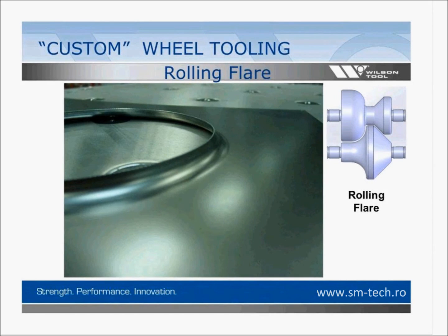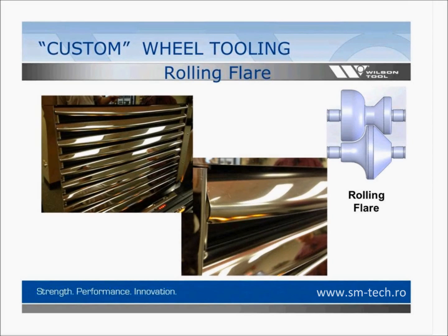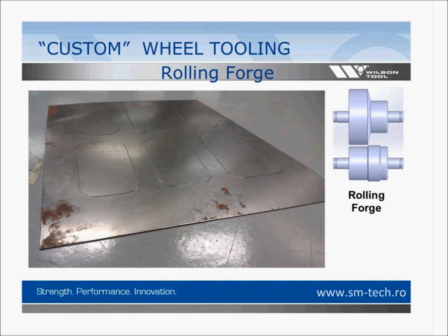Here's what it looks like in a picture, and you'll see that it's not a straight up flange. We call it a flare, so it's a radius going up. However high this flare is, that's what this radius is. And it comes up close to 90 degrees. In this case, it wasn't run around the inside of a hole. It's run along an arced edge. It makes a nice result for these parts. So that was the rolling flare.